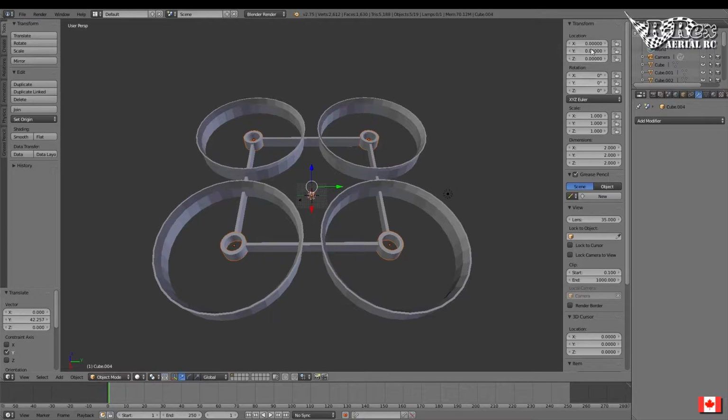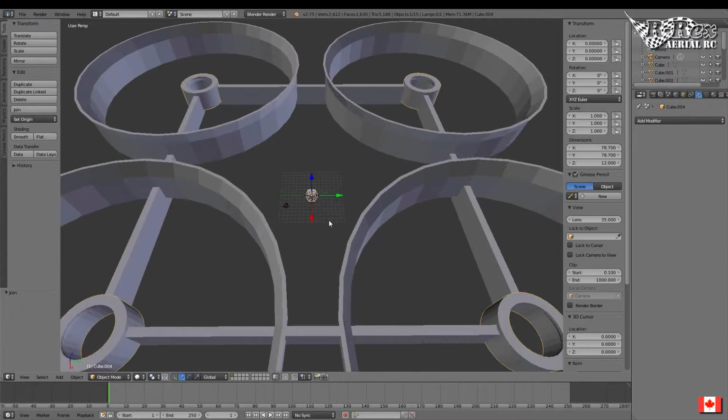And now you'll notice that that puts our location to 0, whereas if it wasn't, the last thing I selected, say that was 34 by 34, is what our total is going to be. So I'm going to select that center, go back over to Tools, and press Join. These are now one object. They're not manifold, in that they're not all connected to each other yet, but they are all one object. I'm going to press Tab,